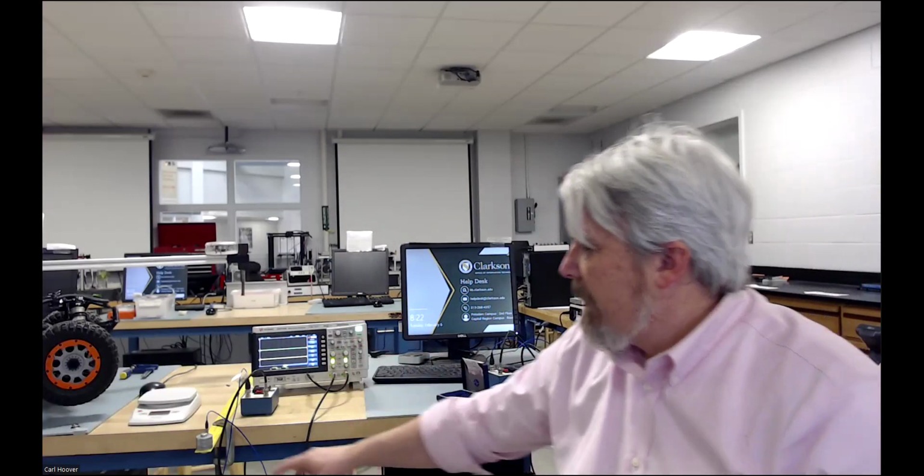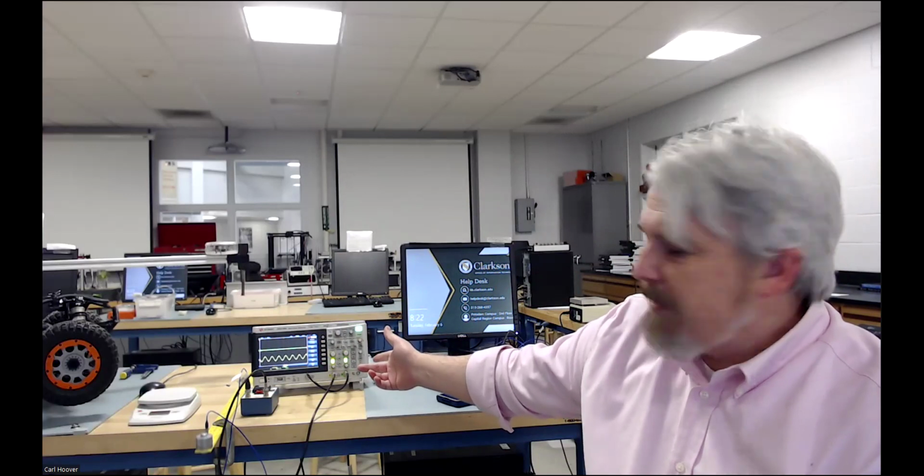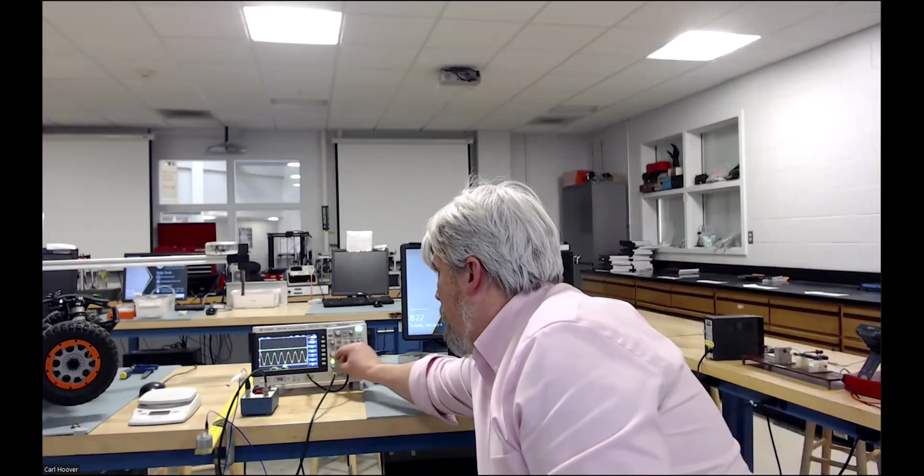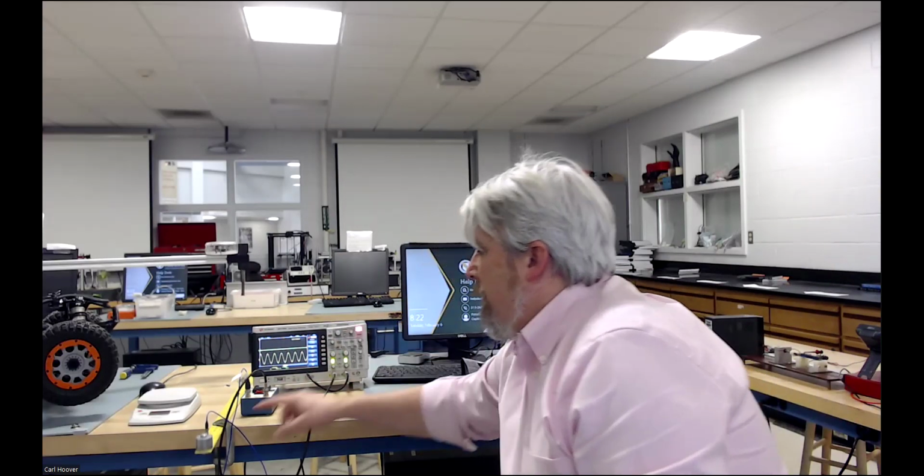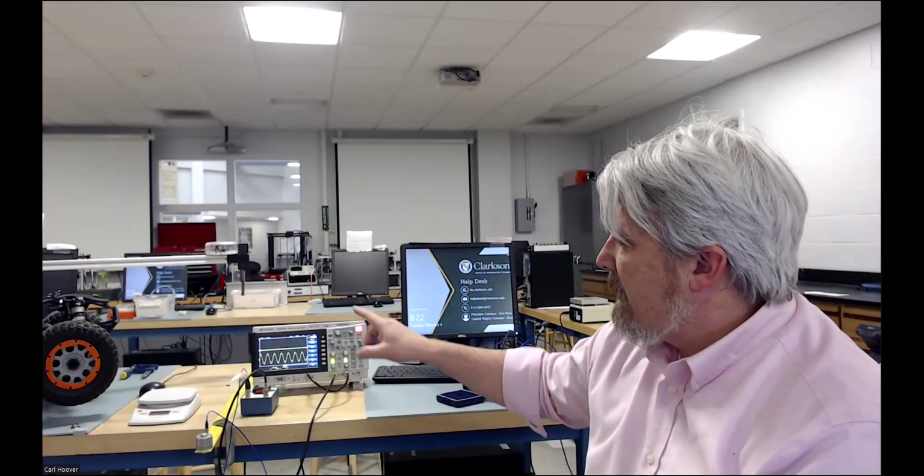This one's currently set up, and if we bounce the accelerometer, it's the yellow channel there. We actually can see it respond and decay over time. And so one of the main things that we're going to do is capture a waveform like this one, and then we're going to measure the frequency and the amplitudes of successive peaks to get the actual damping ratio.